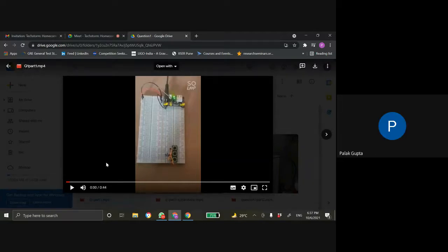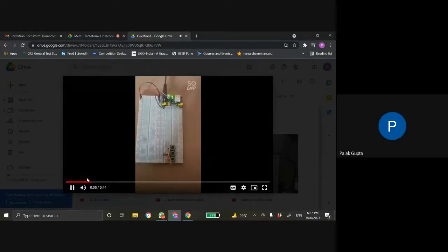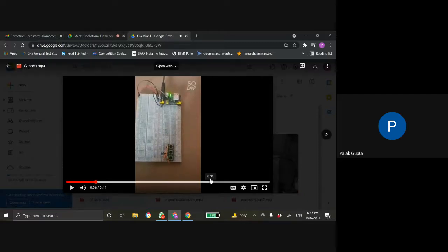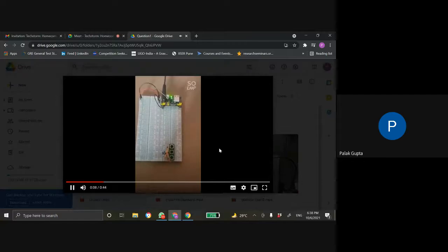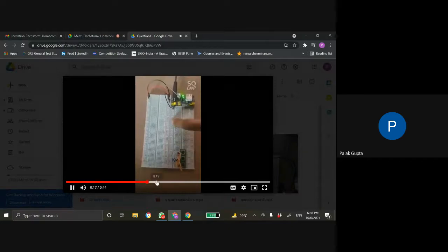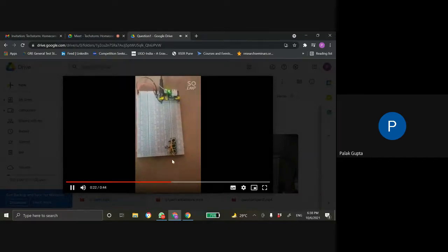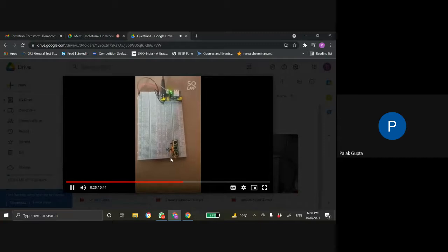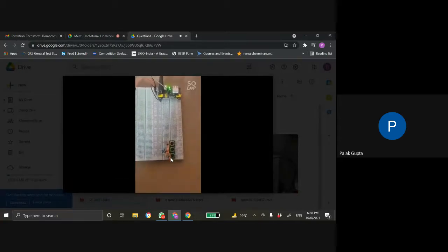You might have these things downloaded, no? In case you're interested. So, in the first part of the first question, we are using three push button switches to control the three LEDs, and we are not using the Arduino. We have done the same question using Arduino also. In this demonstration, we are just pressing the switch, and for that duration, the LED will be on. And we are using resistors in parallel to decrease the resistance because each resistance is of 2.2k ohm.